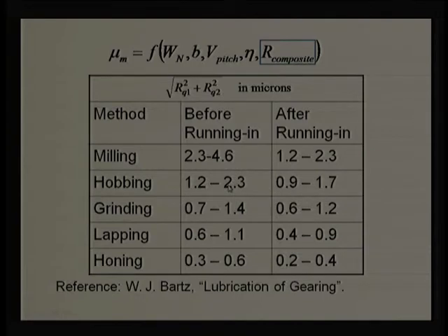We need to operate at the lower speed, remove all the debris, whatever has worn out from the surfaces, and change the oil, and then come to this so that we can do analysis. So, surface roughness has importance. We say we need to take care of surface roughness after the running-in duration.